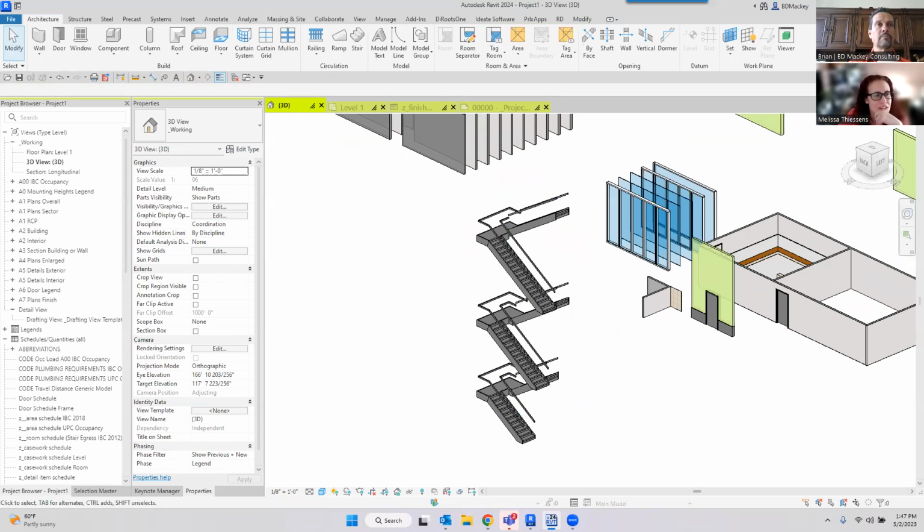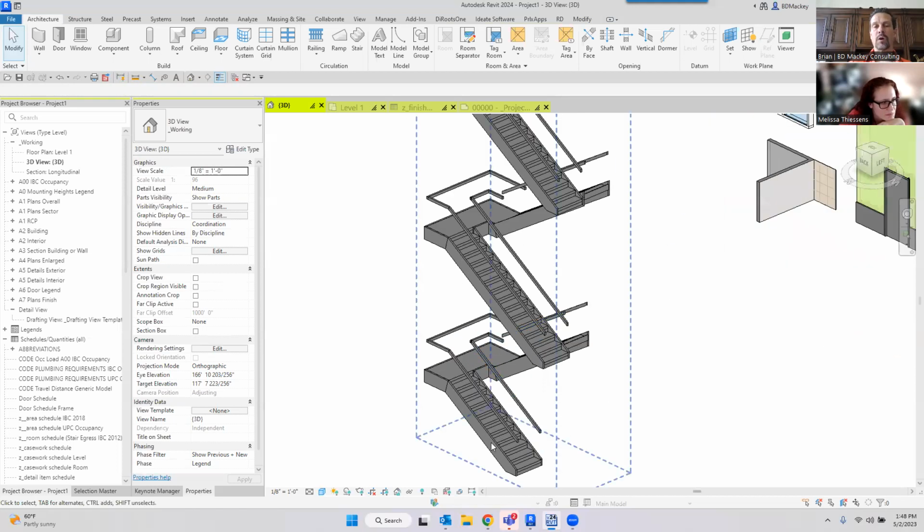What have we got for another? Rick was saying he was trying a scenario where he had a second level that was only a third the distance from the first one, so landings with the first, only one with the second set. Yeah, if you've got multiple landings, no, it doesn't really work. If you're doing a multi-landing stair, that's not going to work with stairs in general in Revit. Well, stairs will be okay. The rails will just completely...